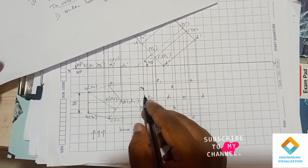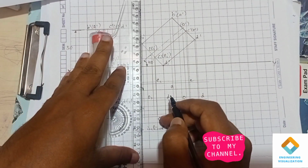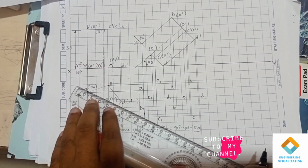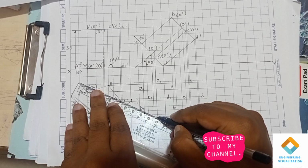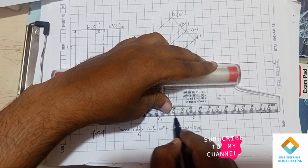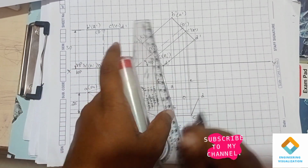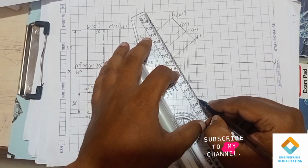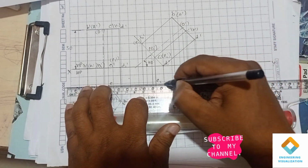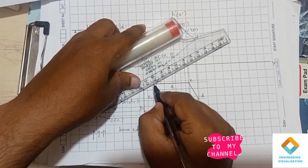So outer boundary line we have to draw, that is from A1 to B1, B1 to C1. We need to connect it using the scale here. So just draw the straight lines connecting it, A1 to B1, B1 to C1, then C1 to C, then C to D, then D to E, then E to E1, then E1 to A1. So this forms an outer boundary line.